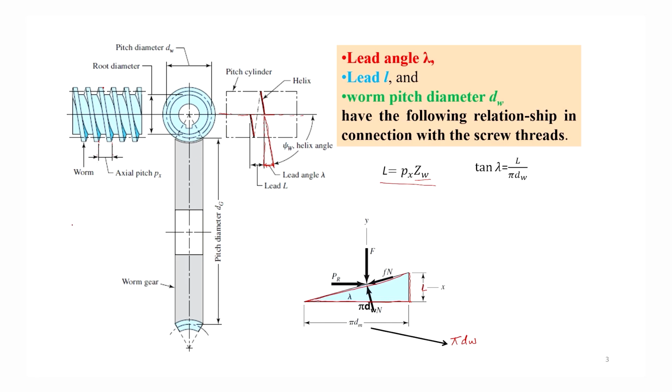The circular pitch of the gear, P, which you may also call C, is equal to pi multiplied by the module of the gear, and the same holds for the worm also. So, this is also equal to the axial pitch of the worm Px. The enveloping gear is shown here, a curved type of structure.